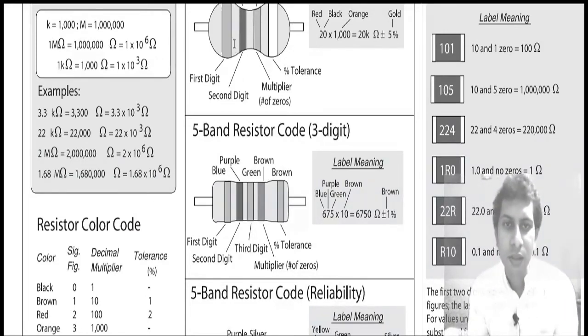If this is a resistor, from this point towards the left side, the first band is of red color. If this is the first band, then this is the first digit. Then the second band, we have the second digit, which is black in color, and the third band should be a multiplier for 4-band resistors. And the last band, which is of gold color, is used for tolerance.